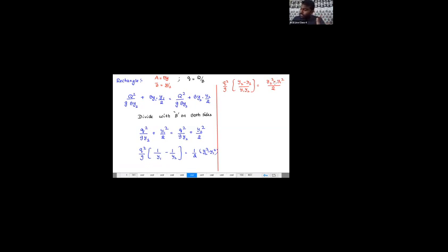So y2 minus y1 gets cancelled. Then the equation I am going to get is q square by g equals, sending the denominator to the other side, y1 y2 into (y1 plus y2) by 2. This is when the specific forces are equal, where y1 and y2 are not